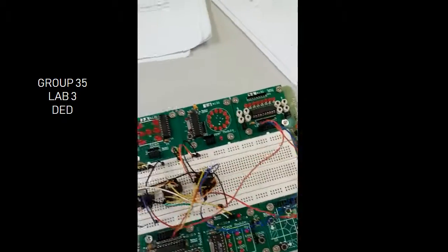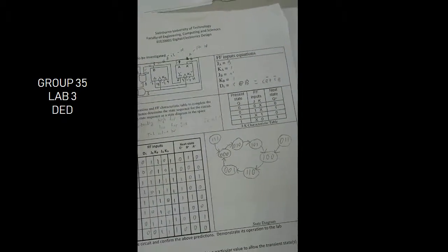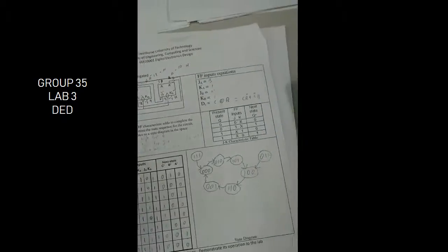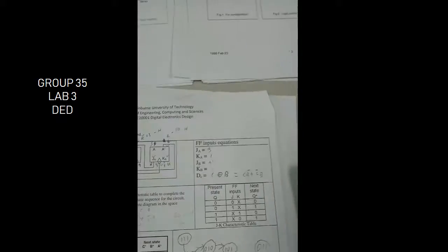So when making this circuit, we have to make sure that the clock input for the D flip-flop is at a high state, because the D flip-flop only changes when the clock is at a high edge, while the JK only changes when the clock is at a low edge. And that's why we use the XOR over here, so that the input to the JK is a low edge from the clock input, making sure that the output from the JK flip-flop is constantly changing to the input.